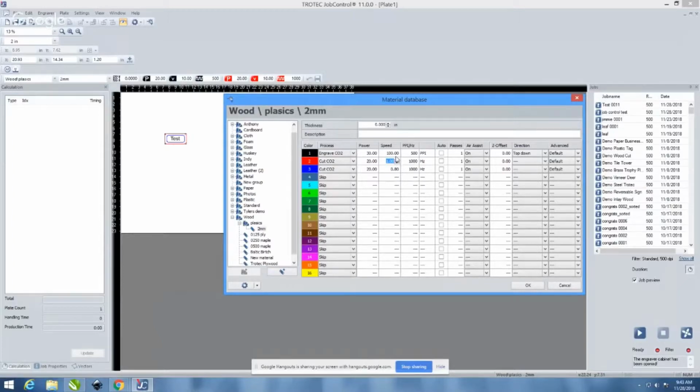Yeah, so just make sure, guys, that you're careful with your engraving settings. It does happen to me almost weekly. You're trying to get your settings in quick, and instead of 1, you might type in 100, and that is not going to be good for your file or your material. Or vice versa, you might type in 0.80 for your engraving, and of course that's going to be way too slow to engrave anything with any good quality. So just keep an eye on that, guys, and you should be fine.